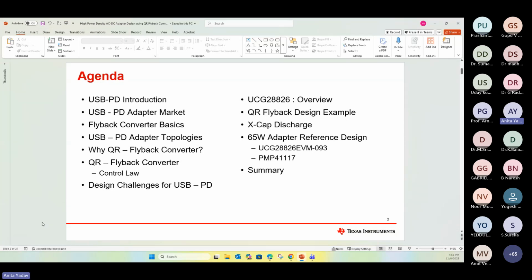So for the particular GaN percentage, I don't have data on that side. But as far as the Indian market is concerned, particularly adapters, yes, it's replacing most of the designs. GaN is the future right now, as it allows you to go for higher switching frequency with ZVS by default. At present I don't have percentage data, but I do know it's already available in the Indian market.